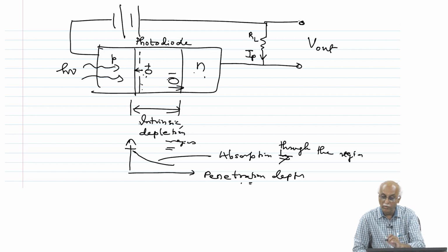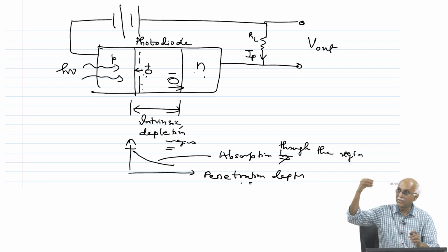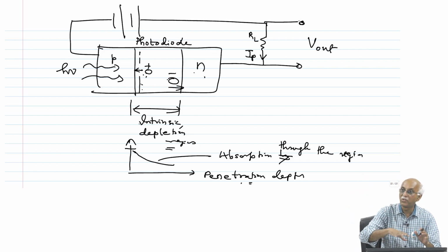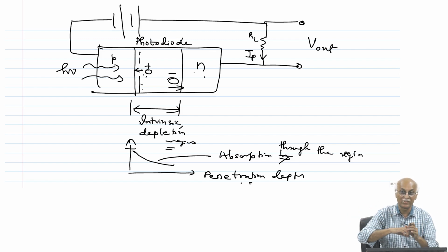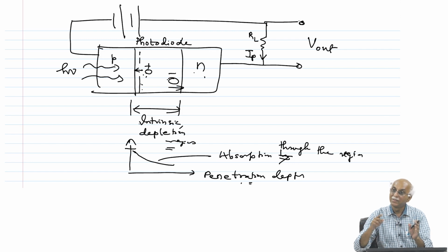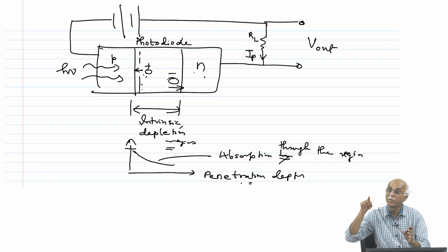If it is forward biased, we can also measure the flow, because when light strikes this depletion region, the resistance will decrease as electron hole pairs are generated. So light-affected resistance decreases. But in a forward bias condition, there is already a current flowing, and on top of it the photocurrent is going to pass.